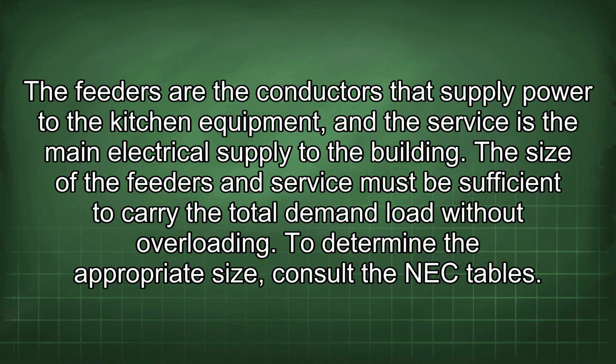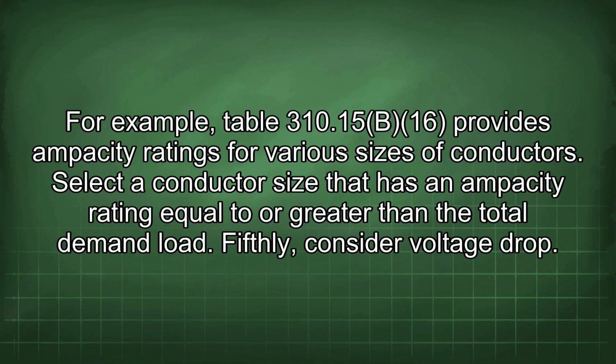To determine the appropriate size, consult the NEC tables. For example, Table 310.15(B)(16) provides ampacity ratings for various sizes of conductors. Select a conductor size that has an ampacity rating equal to or greater than the total demand load.